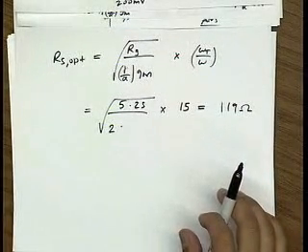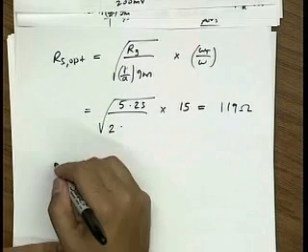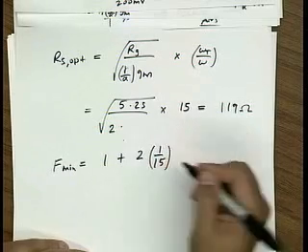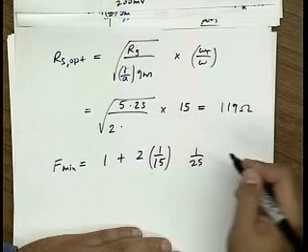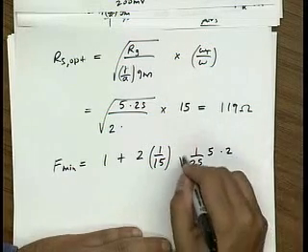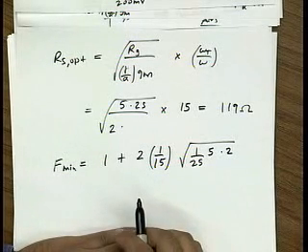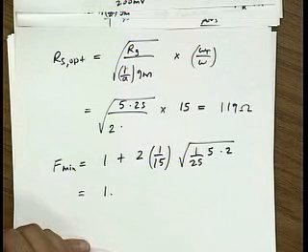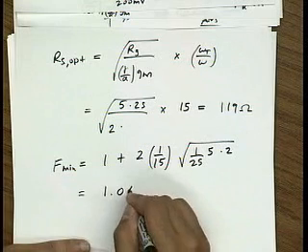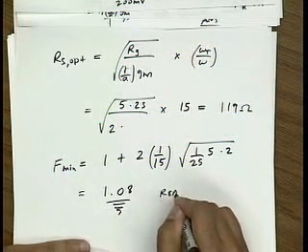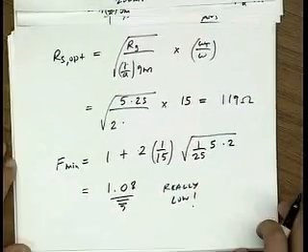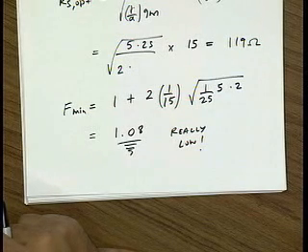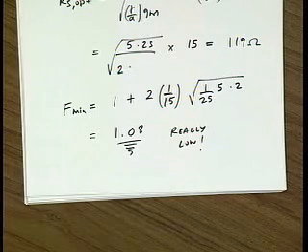Okay, well, what's interesting is if we calculate Fmin, which I was doing before, and somebody with a calculator should help me out here. So this is 2 divided by 15. GM is 1 over 25. RG is 5. And gamma over alpha is 2. So it's the square root of, so it's roughly 3/5 here. So this is like 1.08. Okay, this is really low. This is a sub dB noise figure. If you calculate this in dB, it should be about half a dB or less. Okay, he has an ancient calculator with no log on it.